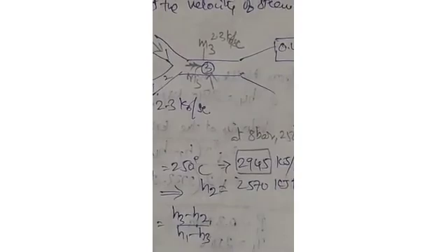Similarly, we can find the enthalpy at the second point. I want to find the enthalpy at 8 bar pressure and dryness fraction 0.9. So we have the 8 bar, already 8 bar is here. Where this 8 bar pressure is meeting the dryness fraction 0.9. As you can see, the slant lines are dryness fraction lines.